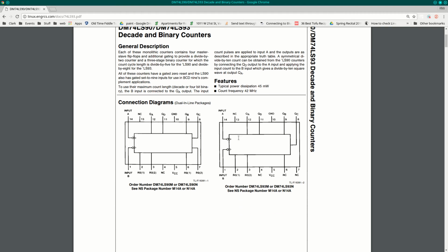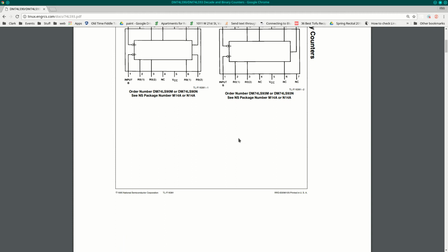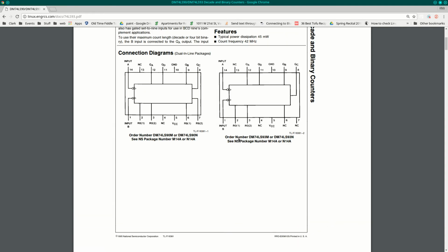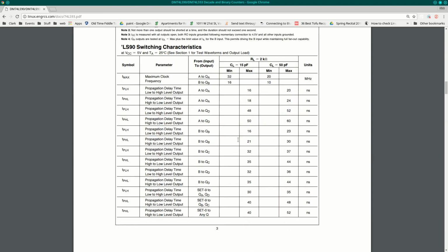What made you think of putting a resistor in? Just curious. I double checked the output coming from the 555 using an LED as well as a resistor running together. And while that was in, the counter would take properly. Okay. So I took the LED out, ran the resistor from 3 to ground, and it worked just fine. Oh, from 3 to ground. Yeah. Okay. That's interesting. I'd be interested in seeing your circuit if you still have it built, because there might be something else going on. But that's a cool fix.